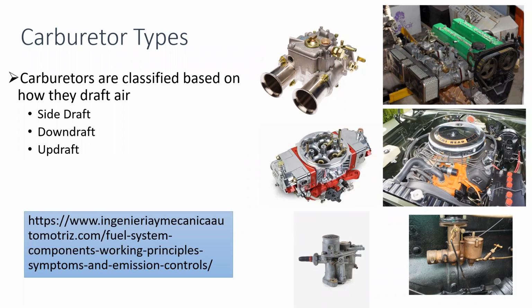But if you consider a modern intake system, it has a few boxes and a pipe with ribs and everything. The reason is that it muffles more noise and reduces the noise level inside the cabin, right? So having an open carburetor system like this looks cool and everything, but it's not the best way.